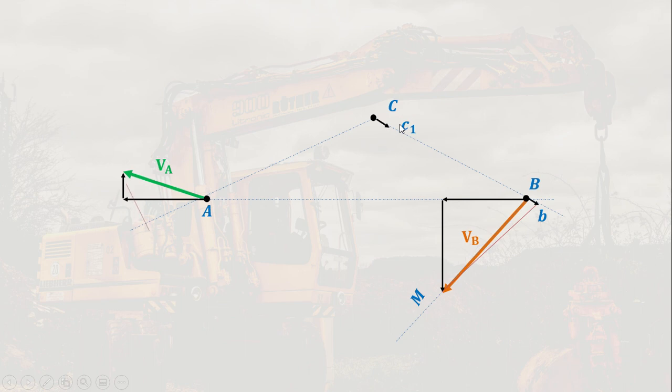And then we will also resolve the velocity of A with regards to the line joining A and C. So as you can see here, this line joins A and C, and we draw a perpendicular line of A, the absolute velocity of A to that line, and then we get the component along. So this is the component along, and also the direction. Since the direction of A is in that, obviously A should be moving in this direction. For B here, since B is moving in this direction, obviously it should move in that direction, so that when you add this one and this component, it will be moving in that direction.